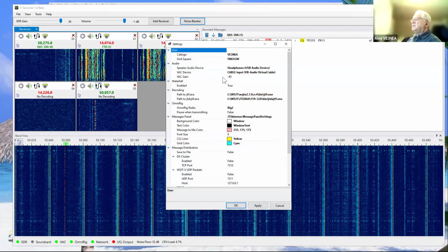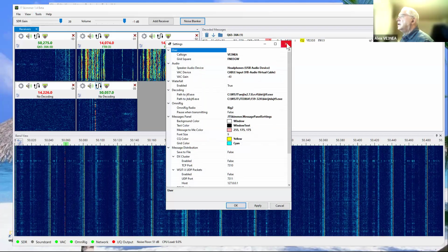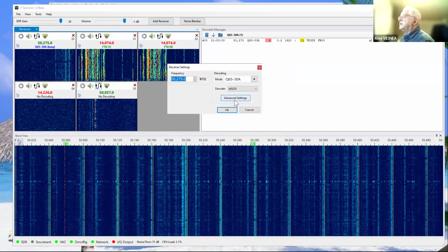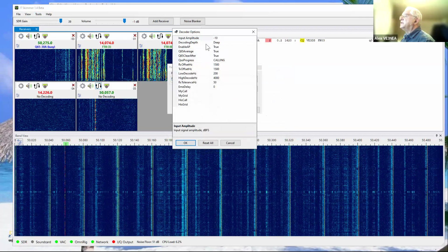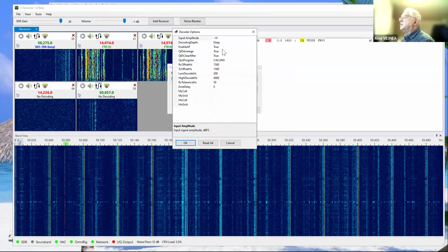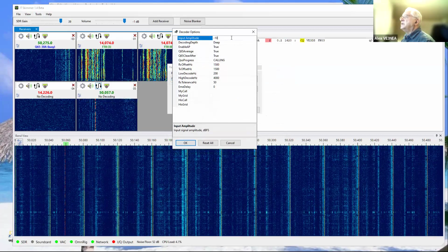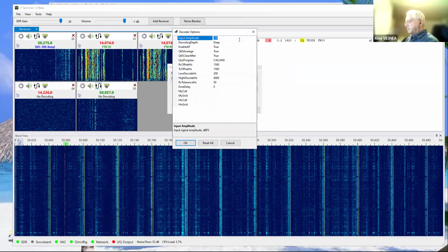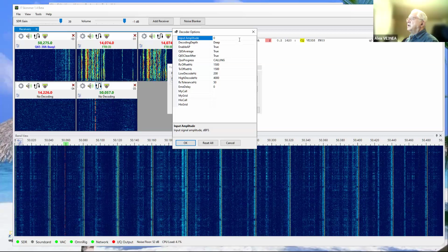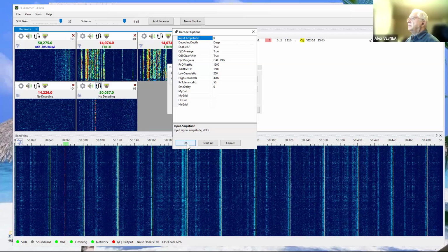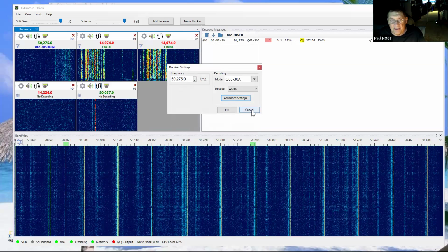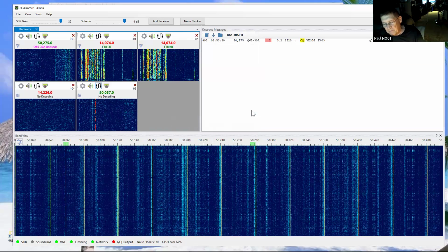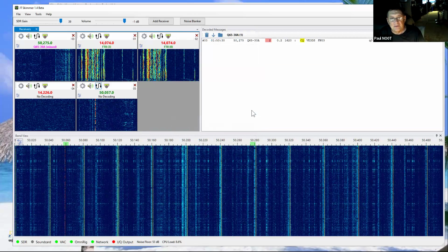Yes. So here you have to set the gain. Oh, where is it? I don't remember now. Oh, yes, I forgot to mention that our decoders have advanced settings. These are the parameters that are sent to JT9EXE when we request a decoding. And here you can adjust the input amplitude. By default, it's minus 10 dB, but someone told me that if you set it to 0, then it decodes a couple more messages. So this is something to try. I have a 10 dB inline pad between my preamp and the AirSpy, and that seems to work really good.